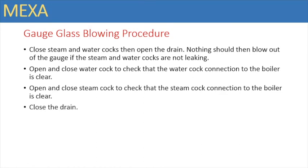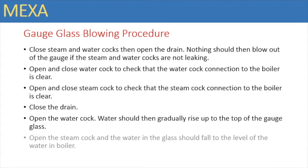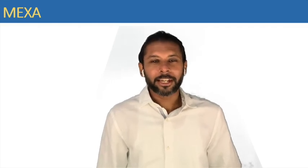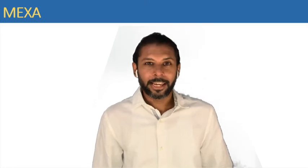Now close the drain. Open the water cock. Water should now gradually rise up to the top of the gauge glass. Open the steam cock and the water in the glass should fall to the level of the water in the boiler. This procedure needs to be done on a periodic basis to ensure that the passages from the boiler to the gauge glass are clear at all times. It is also done to maintain the gauge glass itself.